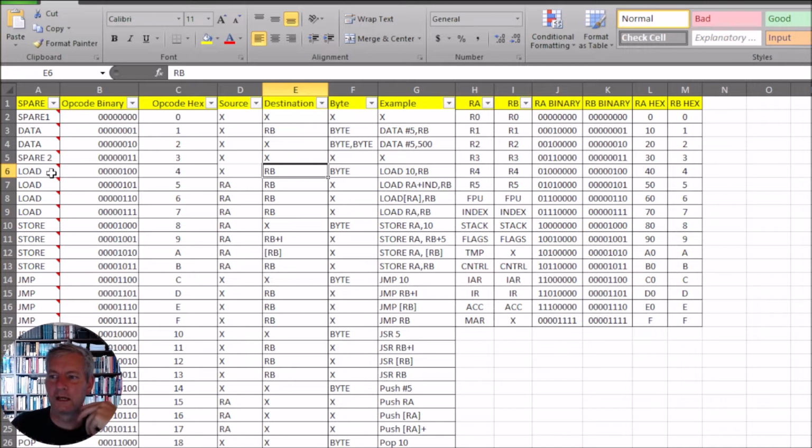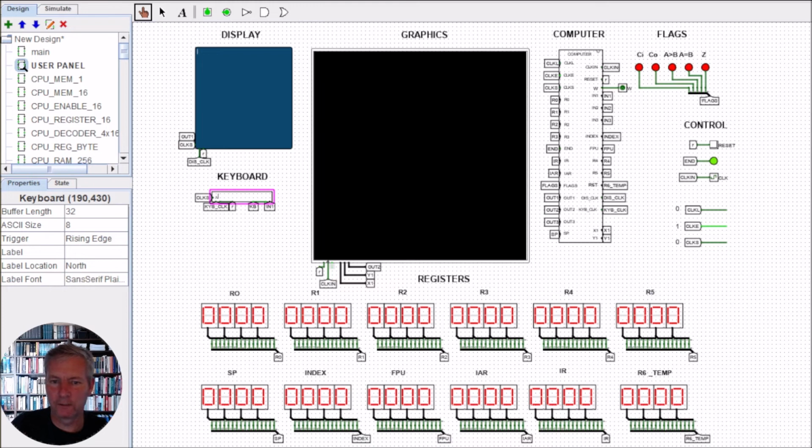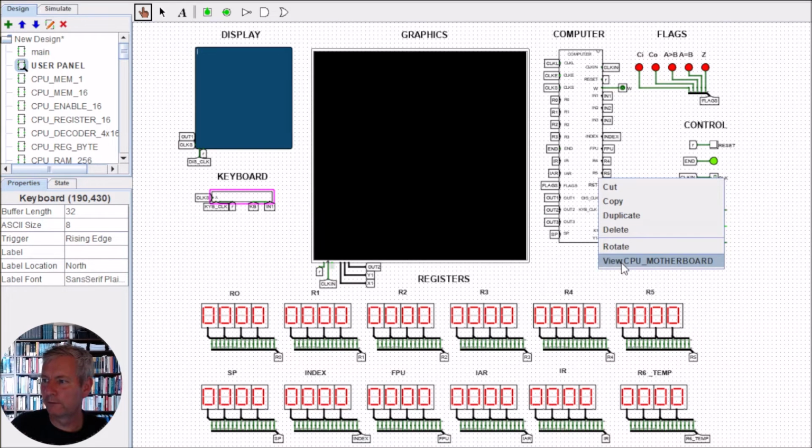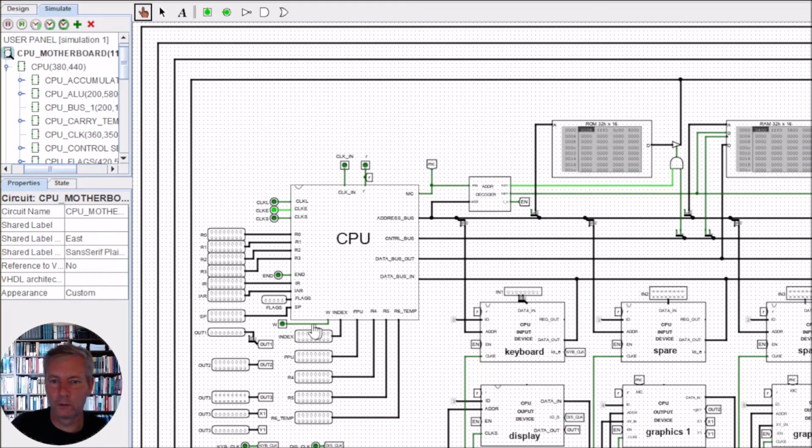But what is the address that we're interested in? Well, we've seen when we worked through the memory mapped IO, if you go back to that video, the addresses that we used for our 16 IO devices were at the bottom of the RAM.